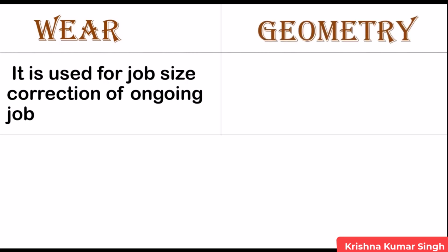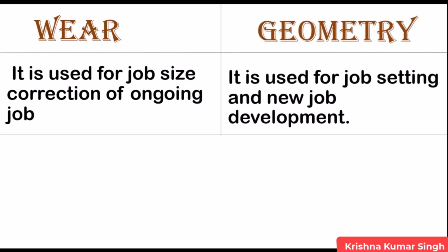2. Geometry offset, used for job setting and new job development. If you are developing a new job, you should use the geometry offset. In production, you use the wear offset, and for new job development, use the geometry offset.